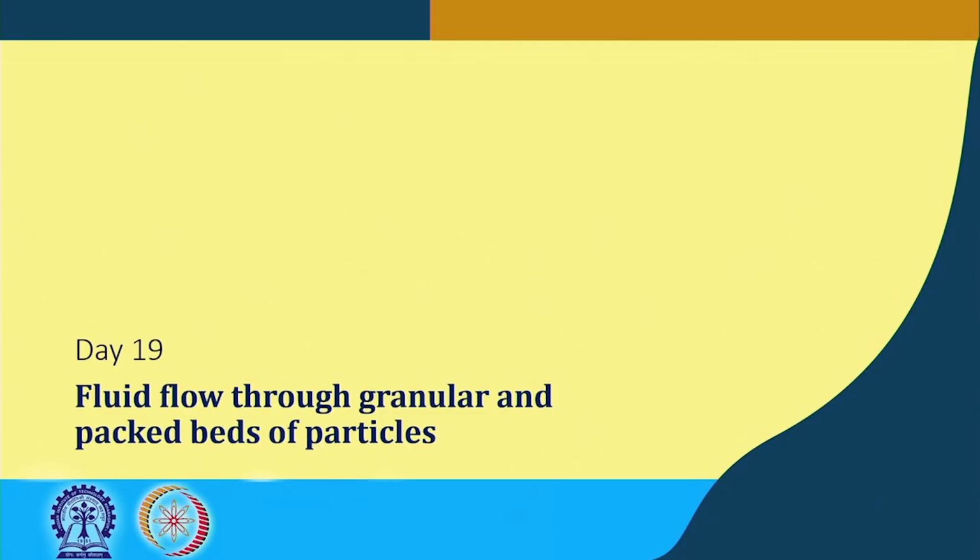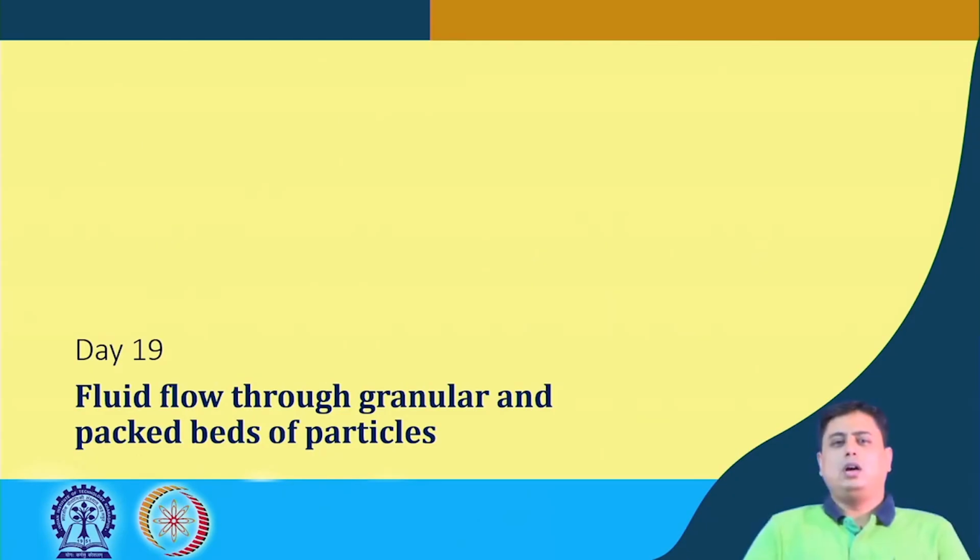So whatever we have discussed till now is the concept of the Ergun equation, the Kozeny-Carman equation, the Burke-Plummer equation, and their range of applicability, when we should use each of such equations, and different parameters in them, like what is the particle Reynolds number, how do we define the particle Reynolds number in the Ergun equation.